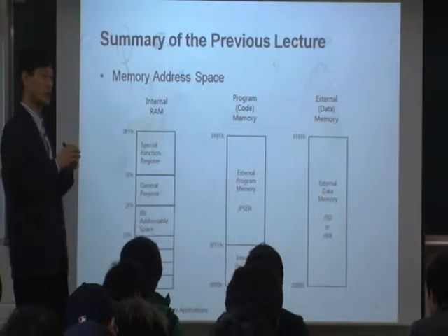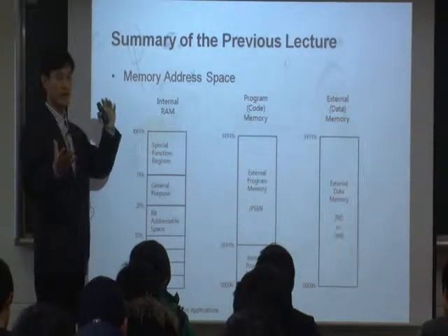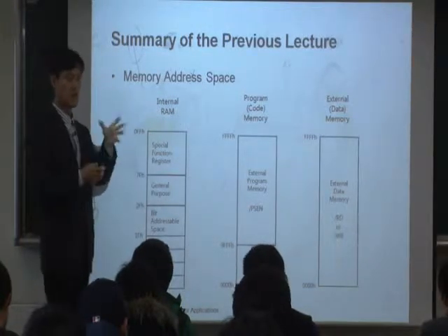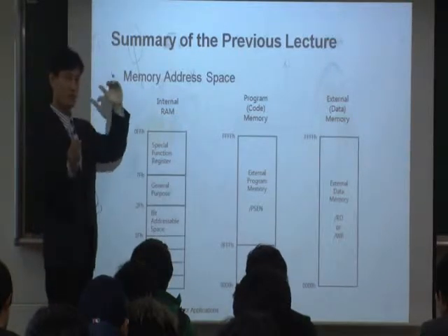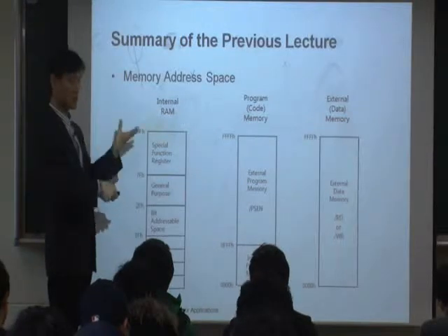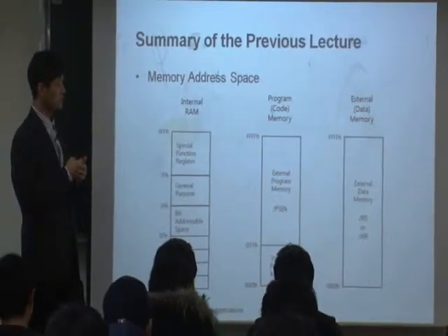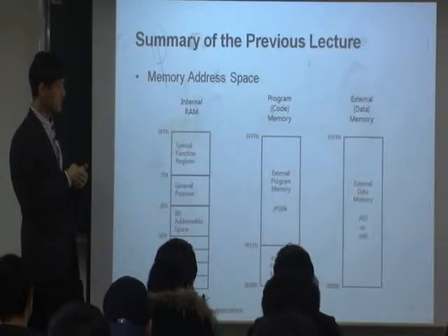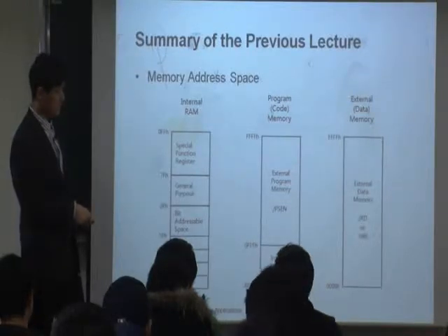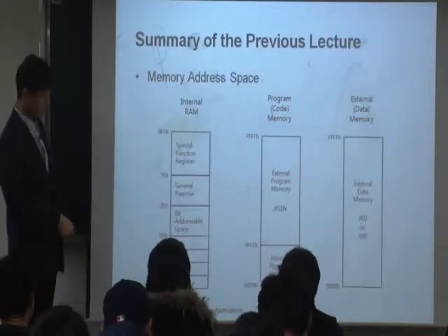Or when you use C, sometimes you declare some array. You know array? Some series of data, right? Those arrays or any other kind of big data should go here. So this is where you put your own values or temporary values or some of the variables. This is internal RAM, and this internal RAM typically goes here, right? Because this is a very special memory.